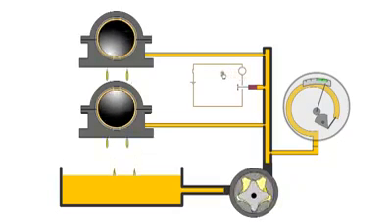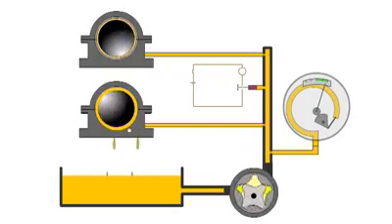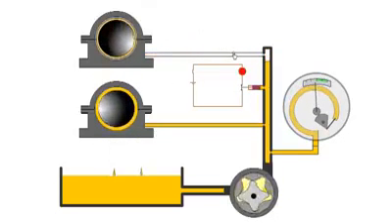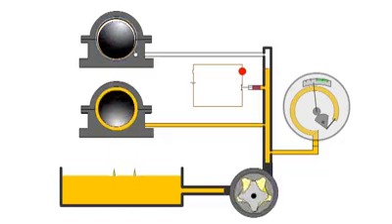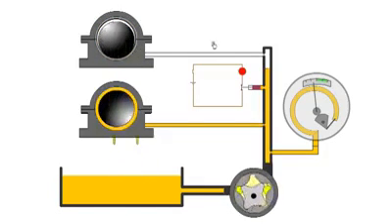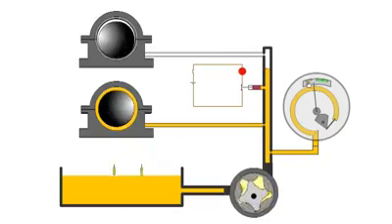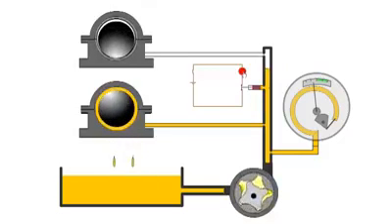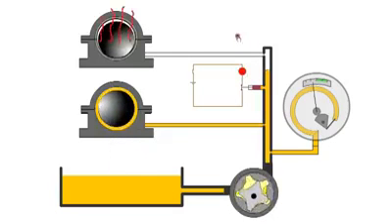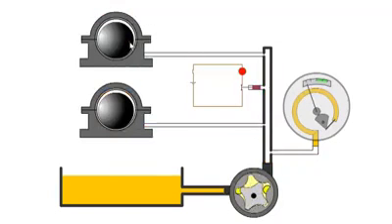If there is wear in a bearing, the clearance will increase and there will be less restriction to the flow of oil. This will result in a drop in oil pressure. Without the correct pressure, the oil will not reach the more remote bearings and they will be starved of oil. Now we have low oil pressure on the gauge and the pressure switch has activated, alerting the driver via the oil warning light. If this situation is allowed to continue, friction will cause the bearing to overheat and seize the engine. Note the low oil pressure was caused by a worn bearing and not due to any issue with the oil pump itself. This is often the case with a high mileage engine.